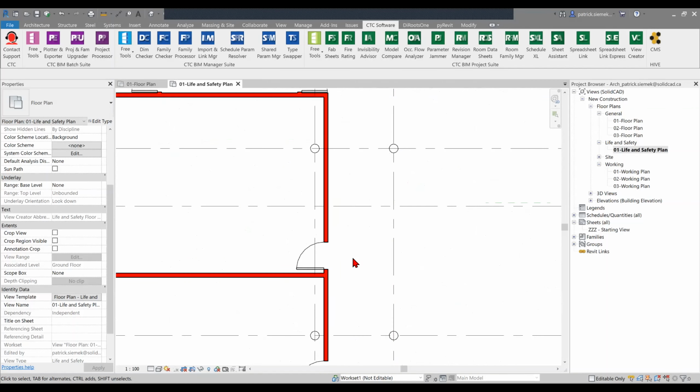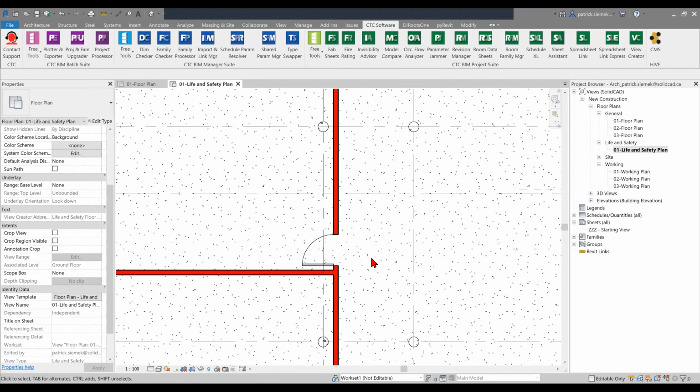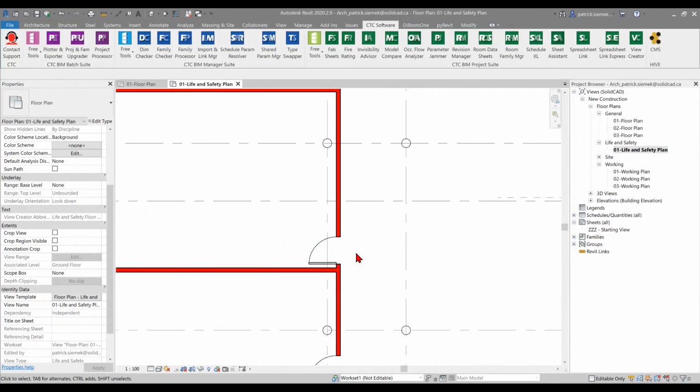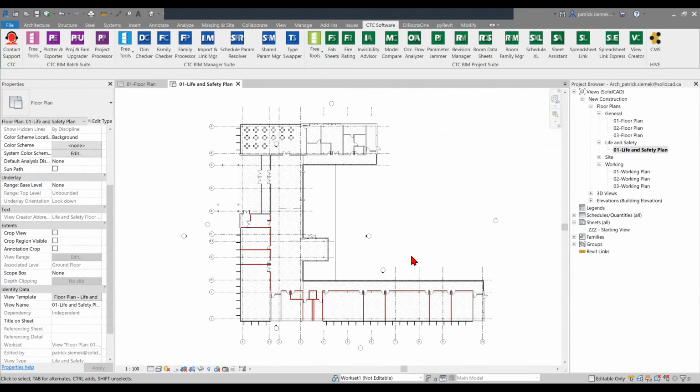And another feature is if we look inside of the door, we can see that the door does not actually have a Fire Rating line going through it. It cuts off at the opening. So what I typically would want is actually a line going through, maybe a customized line, and also possibly some kind of tagging onto that to show a little bit more of my Fire Rating graphics. So filters would just be out of the box Revit workflows.